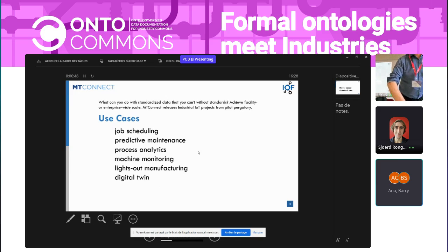And the other two that I forgot to put on here, but the two that we're tracing now, are certificates of compliance and certificates of completion, which are much more interesting in digital twin. So that's when you ask somebody to do something for you, even within your own shop, did they do everything that they said they were going to do? That means not just machining operations, but also things like heat treat, shot peening, coatings, all the rest of those steps.